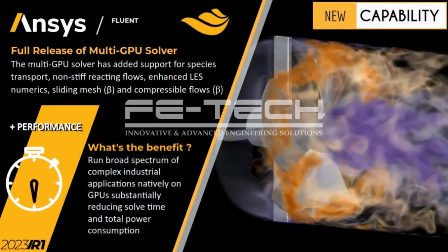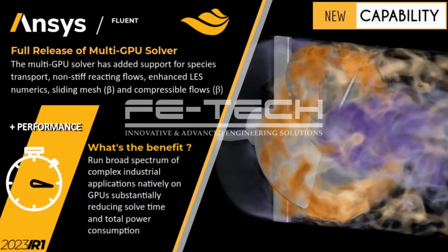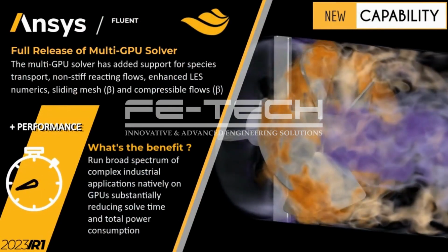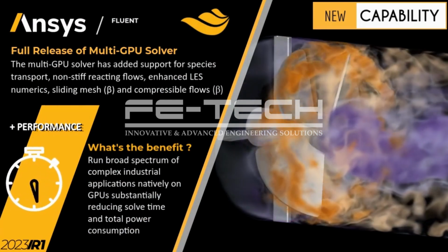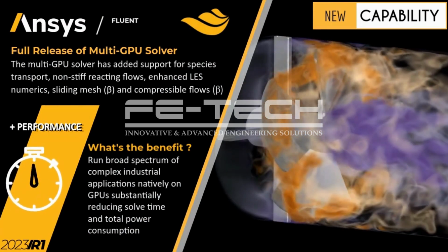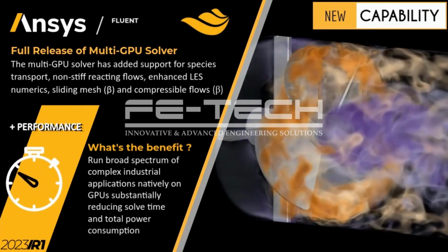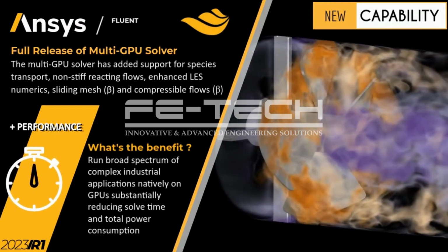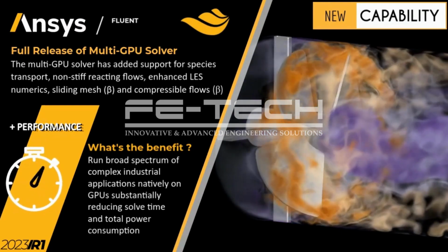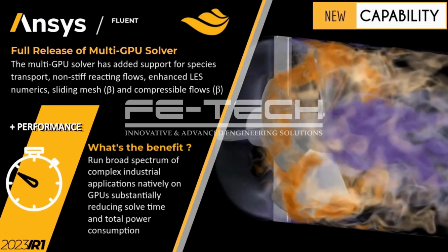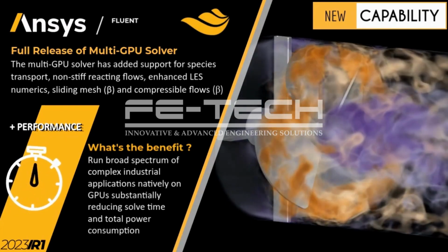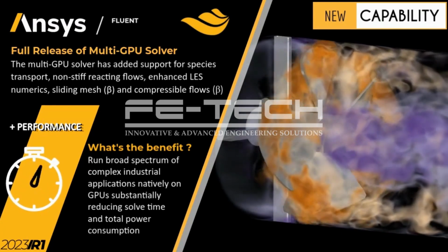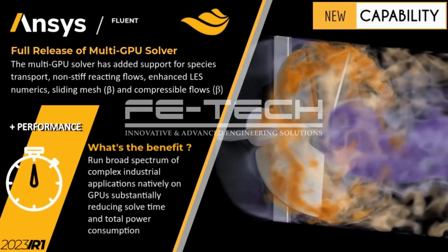You can now run a broad spectrum of complex industrial applications natively on GPUs, substantially reducing solve time and total power consumption, with the results showing 6 NVIDIA GPUs providing the same performance as more than 2000 CPUs. This full release added support for non-stiff reacting flows, species transport, and enhanced numerics for LES simulations. Support for sliding mesh and compressible flow simulation has also been added in addition to the fully released features.